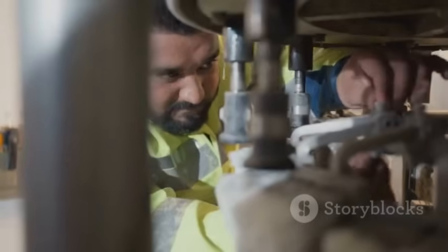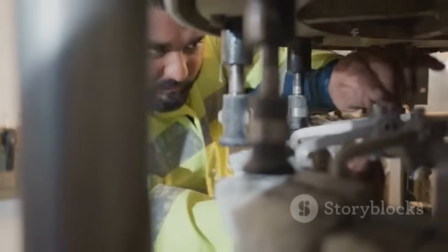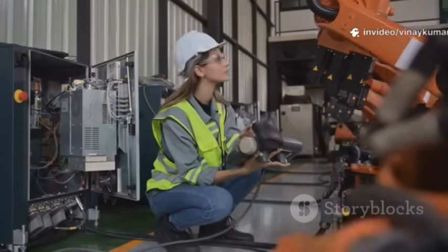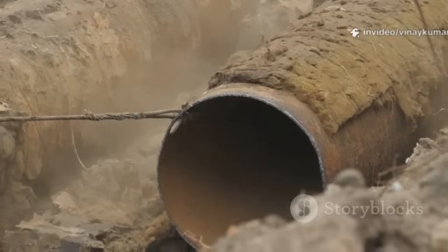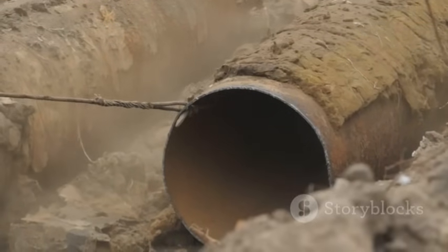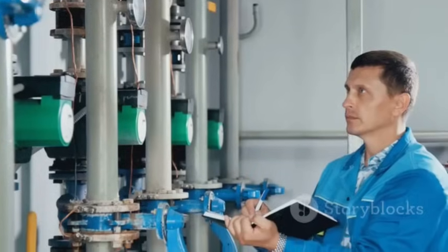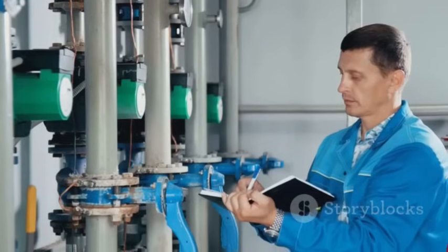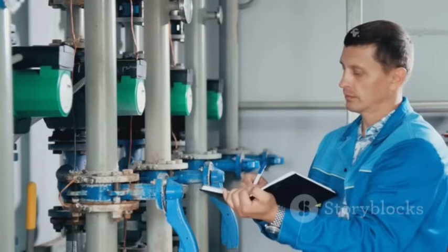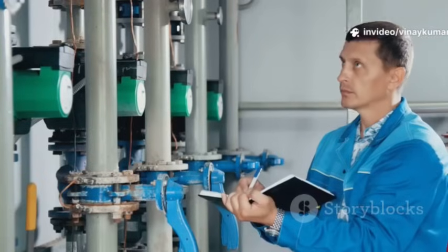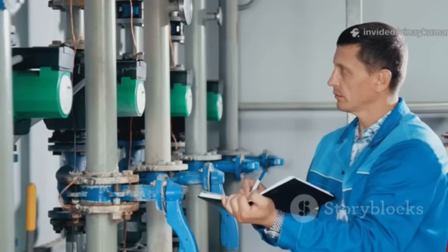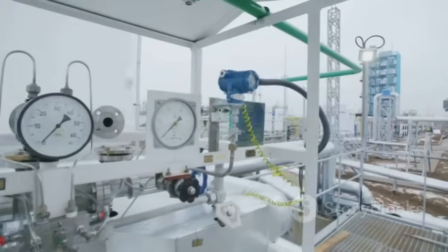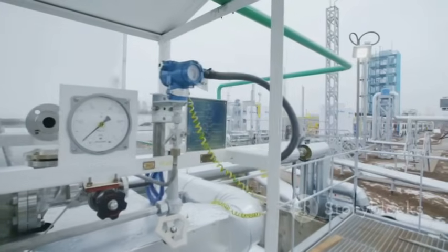It's the systematic care and feeding of your critical hardware to ensure it remains fit for service throughout its entire life cycle. It's about preventing catastrophic failures by catching problems when they are small. The mechanical integrity program applies to specific types of equipment, including pressure vessels and storage tanks, piping systems, relief and vent systems, emergency shutdown systems, controls like monitoring devices and sensors, and pumps.